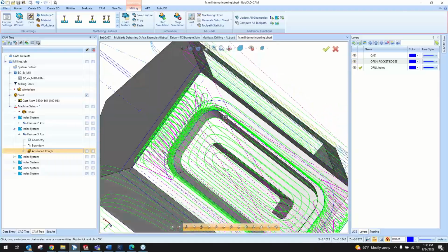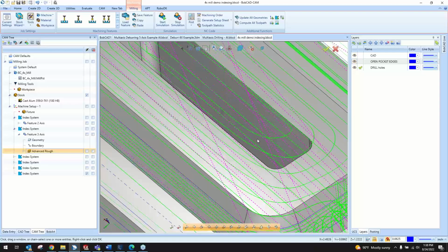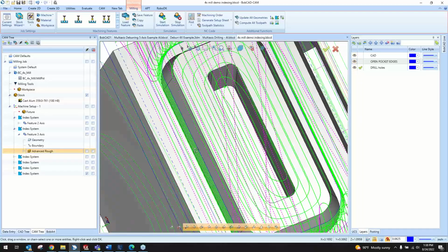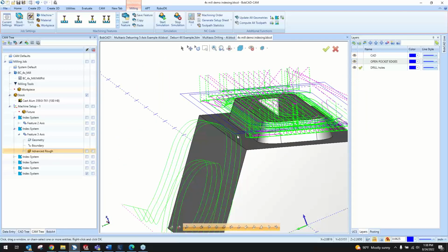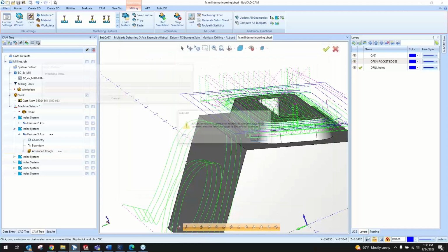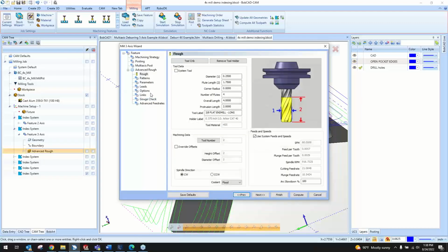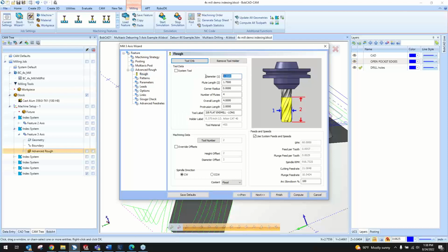I think what it may be doing is from the entry options, and I think a big thing is just the tool's not able to fit in here very much, and it's not able to fit probably based on the boundary here that I've got. So let's make the tool to 1/4 inch instead of 3/8. And then if not, I'll just, we can go into a depth here, so not to waste any time.